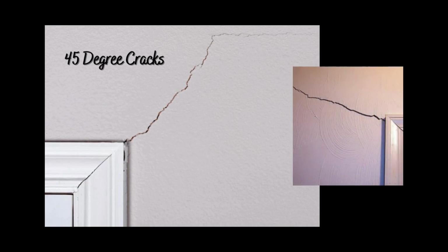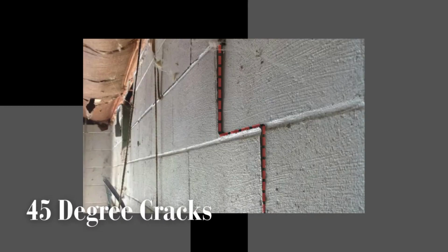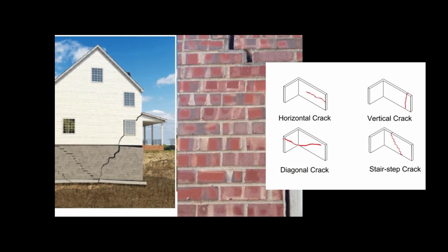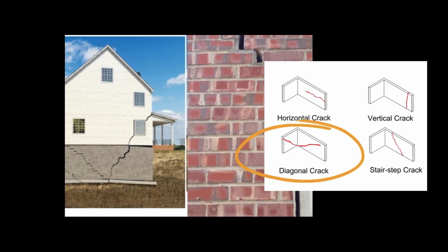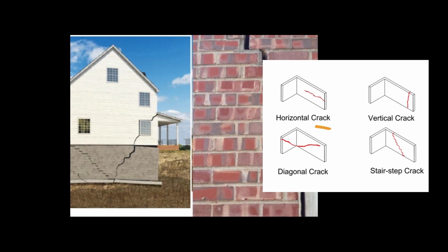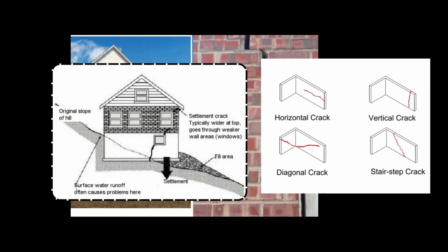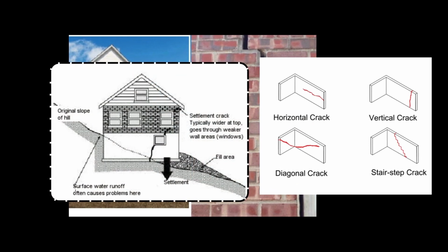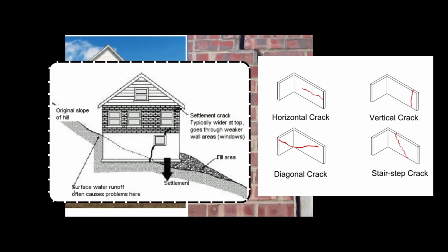45-degree wall cracks are almost always structurally related. The cracks must break through the material to qualify. Step cracks in a block wall, which only crack at the mortar joints and not through the block, are not structurally related. When the bearing or foundation under the wall is not adequate, the wall will settle or sink at the weak area. The adjacent wall structures, which are adequately supported, will resist this movement. This situation will cause the 45-degree cracking.